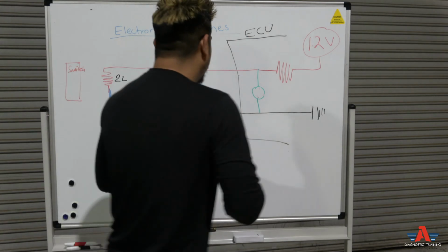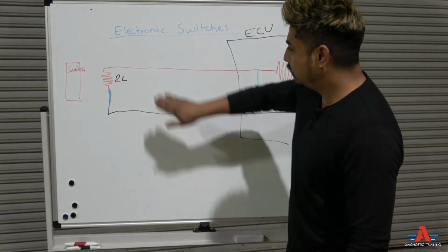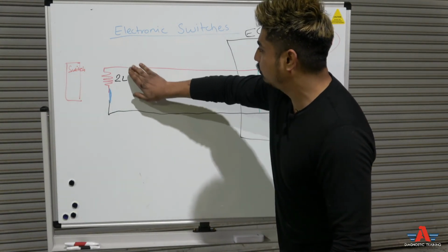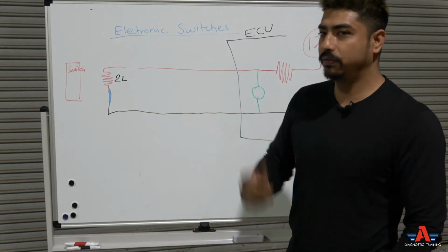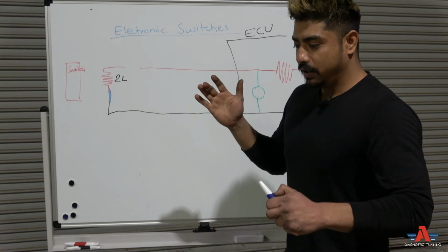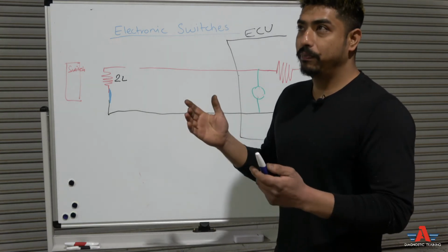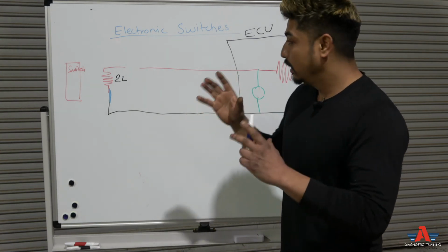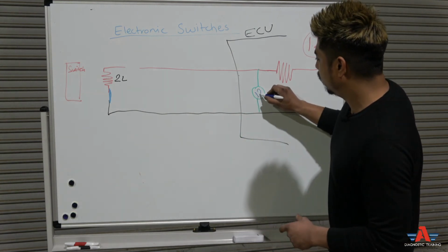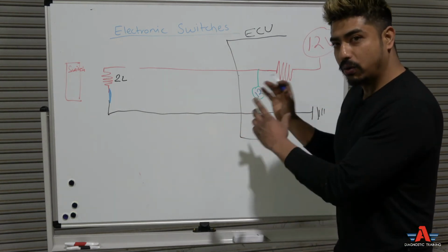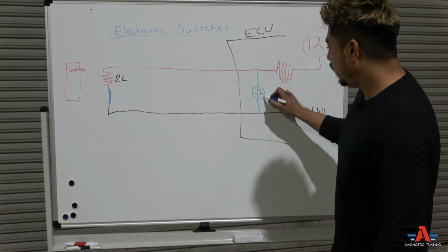When you had the open circuit, when you disconnected the plug right here, that's what the fault code was: voltage shorted to battery. It means here it was seeing 12 volt, okay?